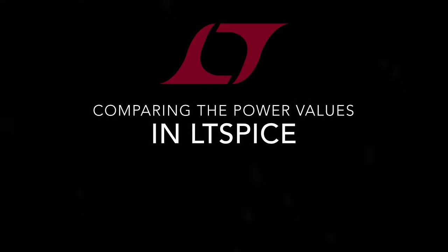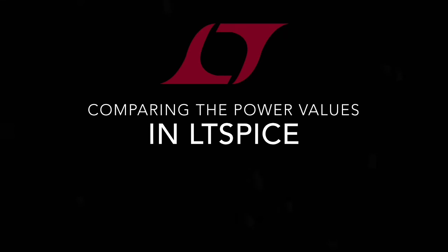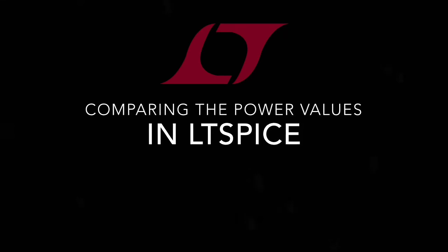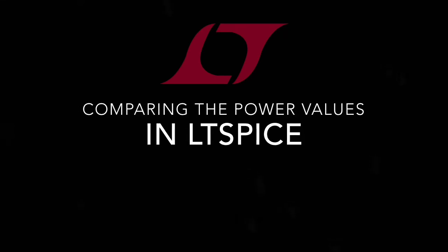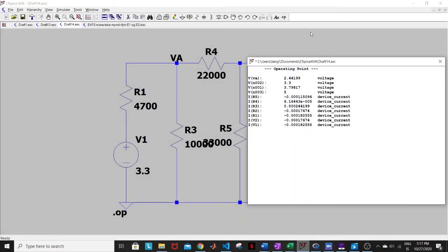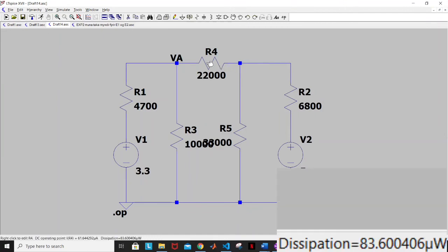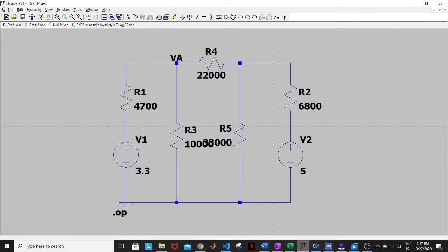To make the calculations easier, we are going to use LT-SPICE to prove that superposition cannot be used to find the total power dissipated. It can be done when performing the simulations. When hovering the mouse over resistor 4, the power dissipated by the resistor will appear down in the left corner.